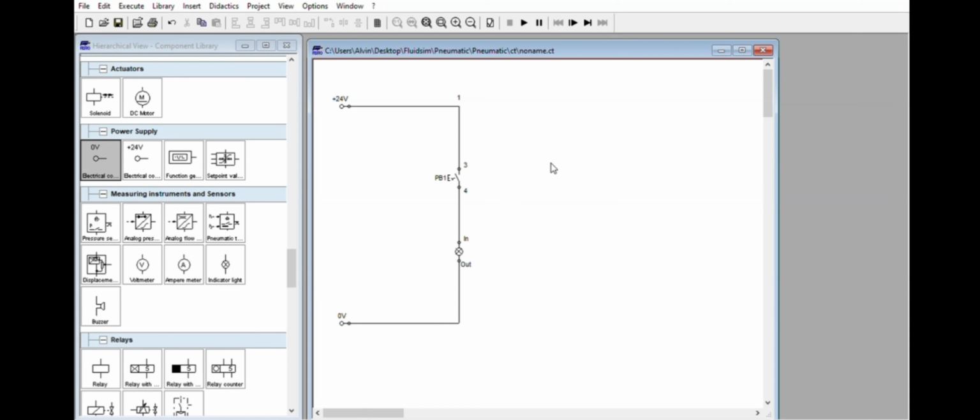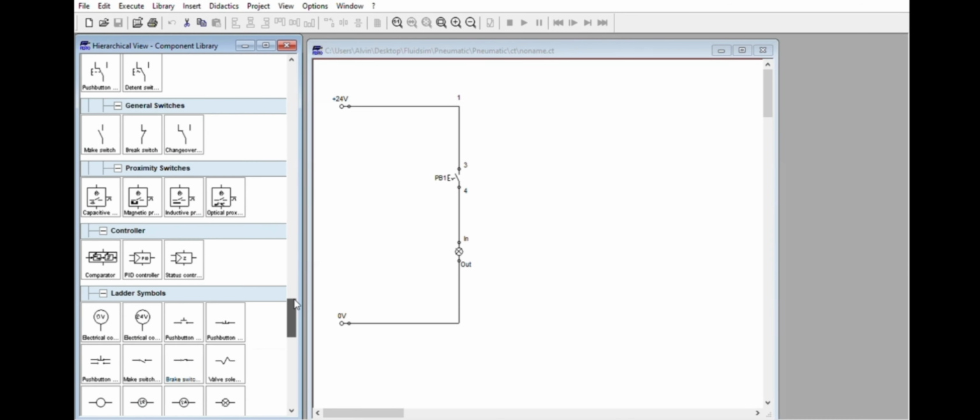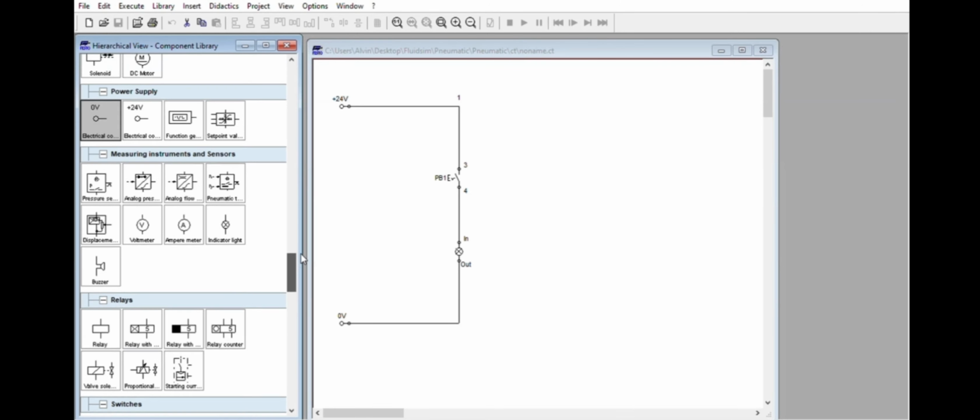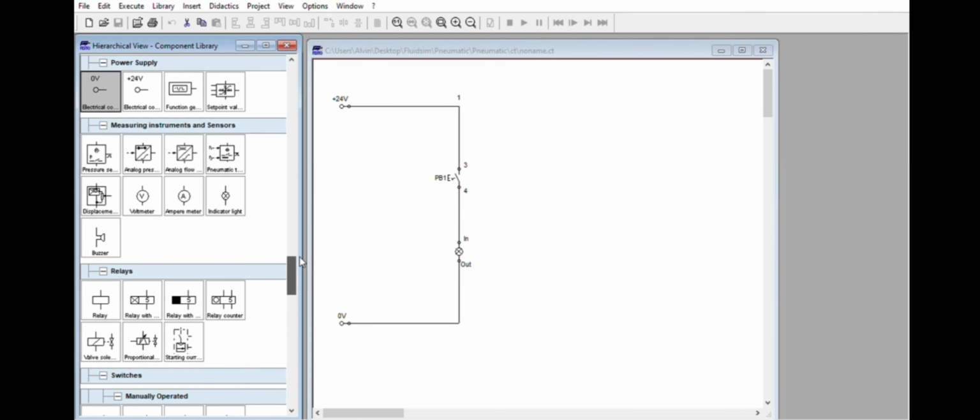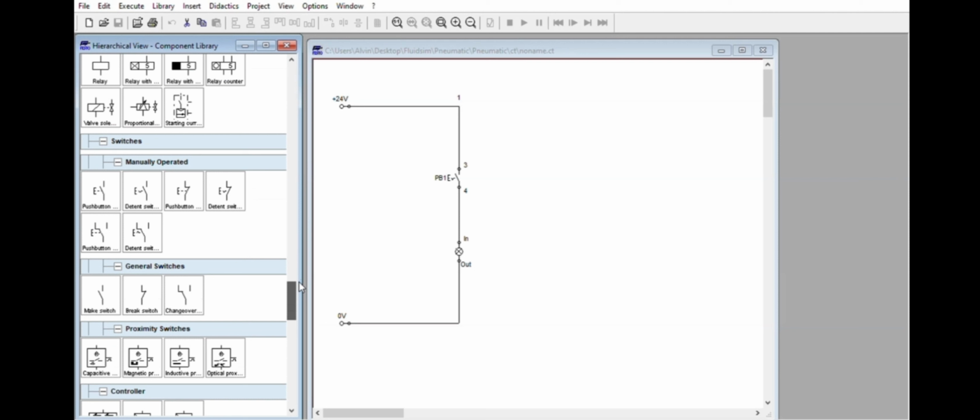In ISO, the normally open contact is usually pre-labeled as 3 and 4. For the normally closed, it is labeled as 1 and 2. So that is usually for IEC standard. If you have another set of contacts here, that will become another 1 and 2.